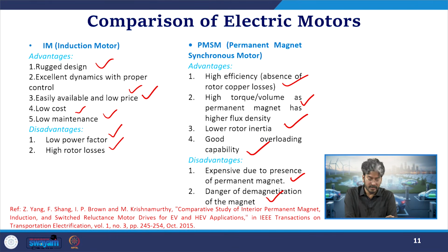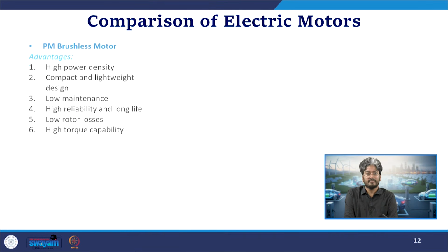When we go into this PMSM, we will see what are the materials which will be used to develop the permanent magnet, and we mostly depend on imports for manufacturing the PMSM magnets. And the other limitation of this permanent magnet is, over a longer run, it has the tendency of getting demagnetized and the performance of the motor may not be maintained over the lifetime of the vehicle.